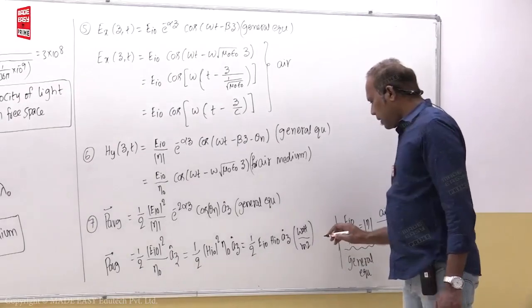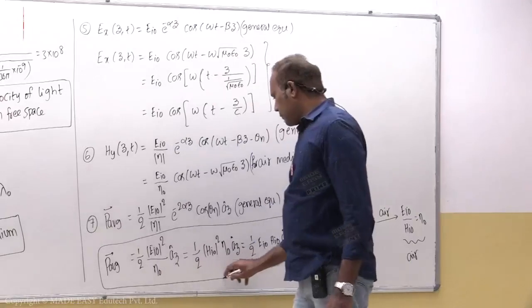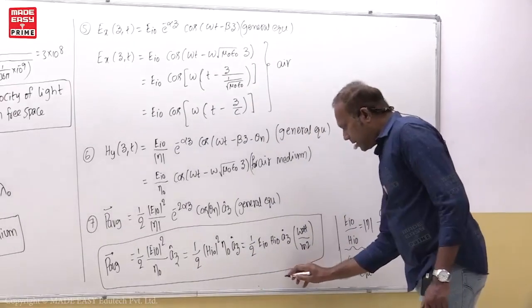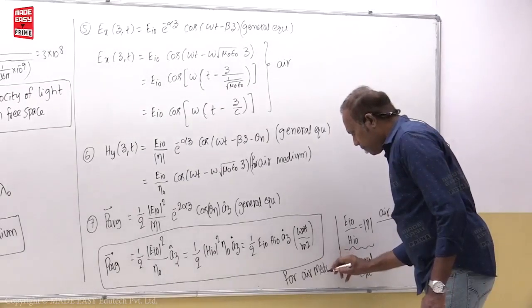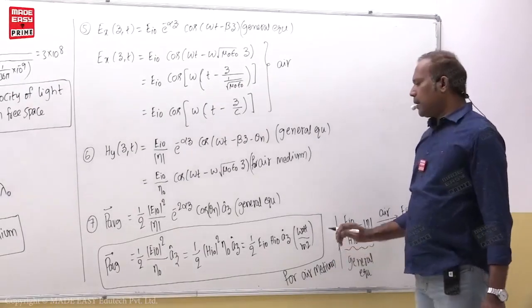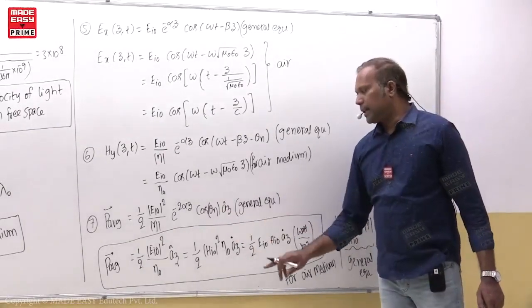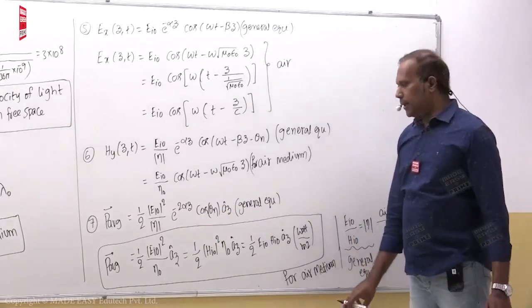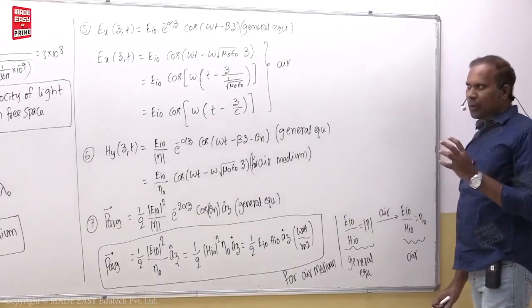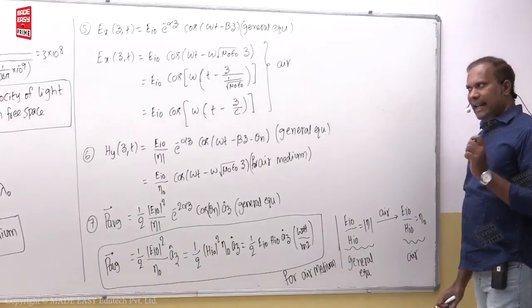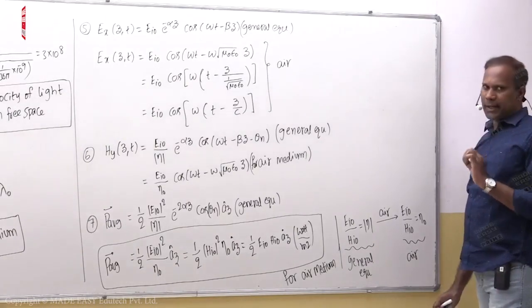So this is for air medium, and I am putting this in the box, because you have substituted air medium parameters. For air medium, alpha is 0, theta eta is 0, modulus of impedance is eta naught. So the next discussion will be wave propagation in lossless dielectric, or otherwise it is also called a perfect dielectric. Okay.